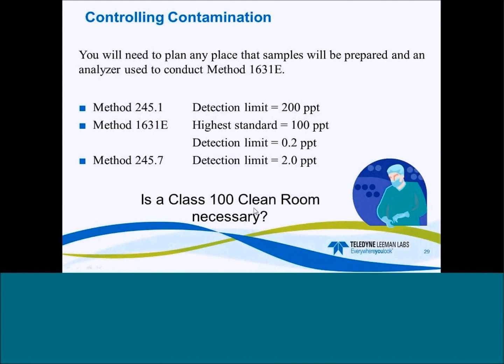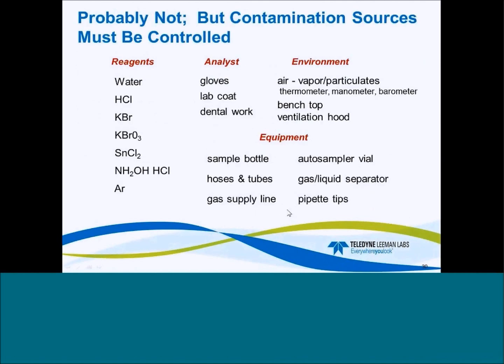The question becomes to many people, do they need a Class 100 clean room? And in our experience, we found that that's typically not required, but you do need to control your sources of contamination.